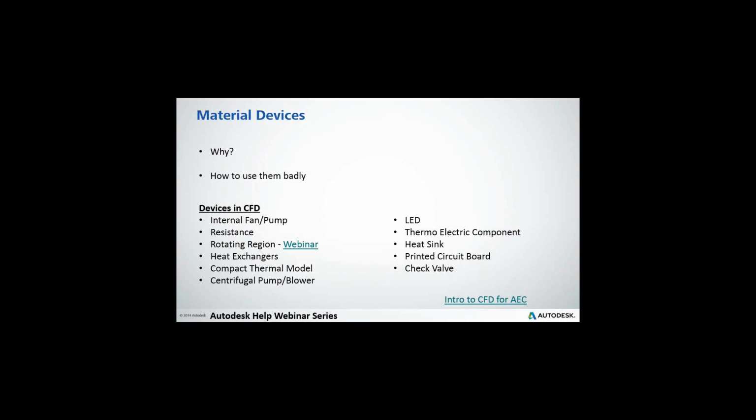What I'll see is with something like a CTM, there's a theta JB and a theta JC. Essentially, those are ratios of how much heat is going to go to the case of a chip and to the board. A lot of times you will find that published by manufacturers, and in that kind of case, it is important to be fairly correct because you can put heat in the wrong area, and then it's not working the way you intended. But if you're using the same assumption across the boards, at least you'll be trending in the right direction. Kind of my take on that.